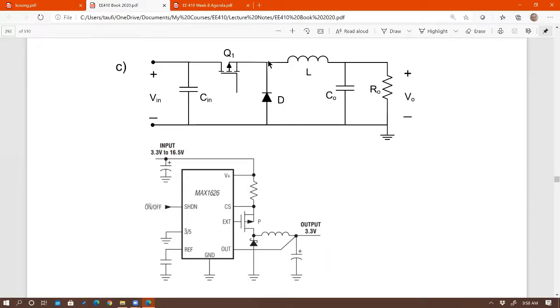So if you put an NFET, it's not going to work, because this is going to be changing unless you do something else to this gate. A simpler way is to use a PFET. The drive goes from gate to drain, and the drain is constant. So now you have a stable gate to drain signal to drive the PFET.